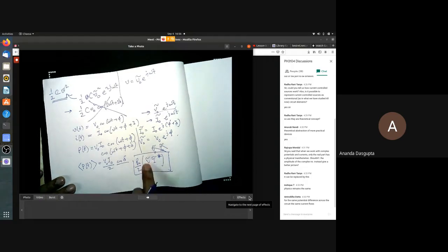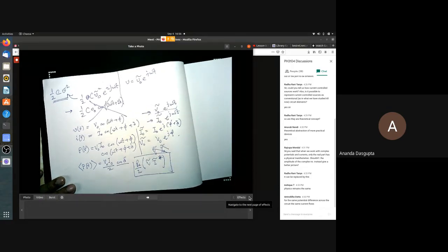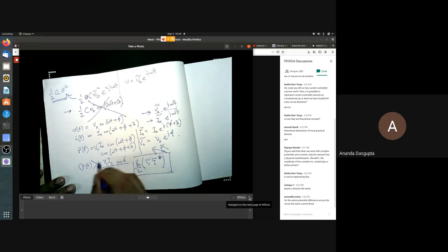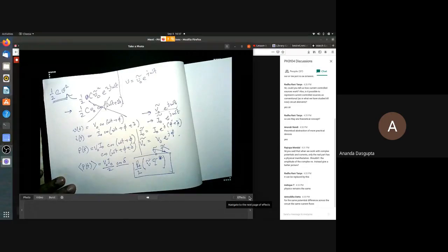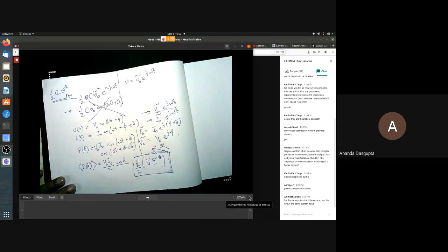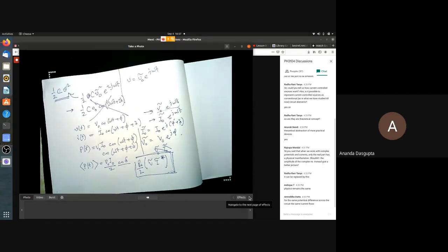Because the moment you do this, V tilde I tilde star, the e^{j(omega t plus phi)} cancels out because of the conjugation. If the j delta is the only thing, either it is e^{j delta} or e^{minus j delta} that survives. In both cases, if you take the real part, you do get V0 I0 cos delta, and you throw in a half from outside. Okay, so this is the formula you would have to use for the power if you are using complex exponential voltages and don't want to give up on that.